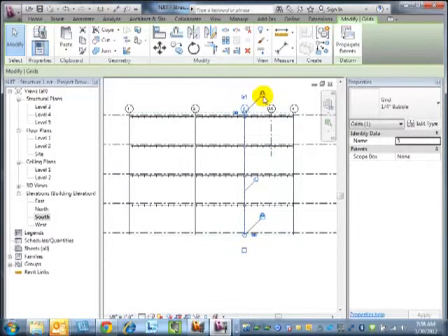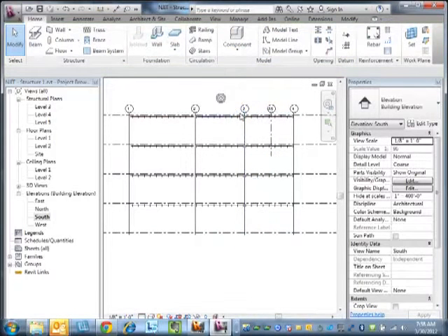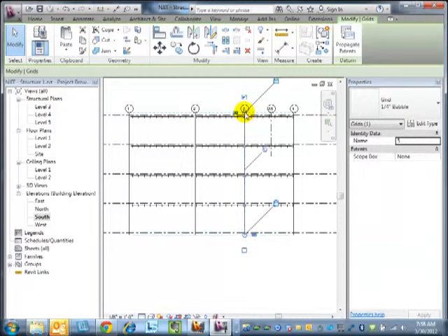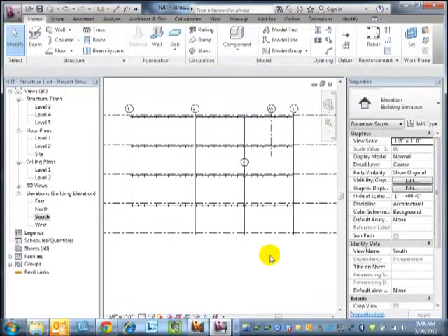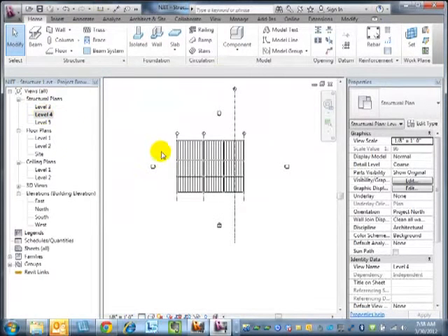If I unlock the top of it from the other sides, then I can go through. I thought I unlocked you. Oh, it's pinned. Doesn't like that either. So now grid 3 will only apply to the lower floors. Up on level 4 and 5, 3 isn't there anymore, but 3.5 is there. So that's how you can control grids at that level.